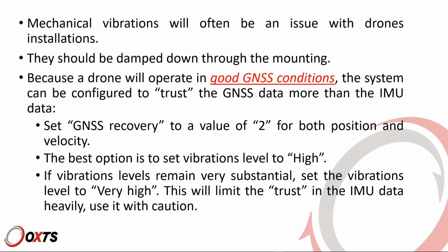The other thing is that we need to set the vibrations to high, not to normal, but to high. If your vibrations are really bad, you can still set the vibrations to very high, but keep in mind that if you do this, the trust in the IMU data will be limited heavily. So use it with caution.